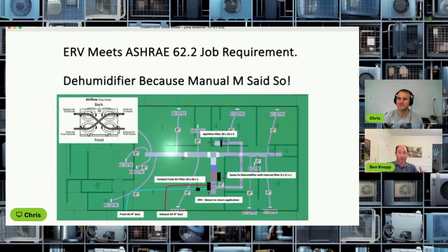It was like 13,000 BTUs was the minimum. It can't even go down to 1-ton output. Well, yeah. Our load at the dehumidification design conditions was below that. It was right at 1 ton. Well, that means that when we need to remove the most moisture, our system is cycling off.